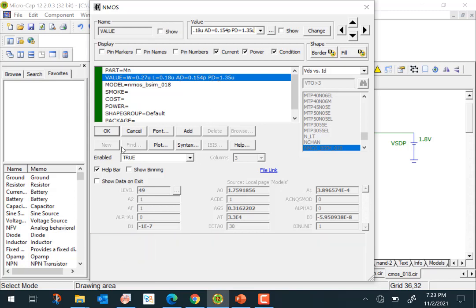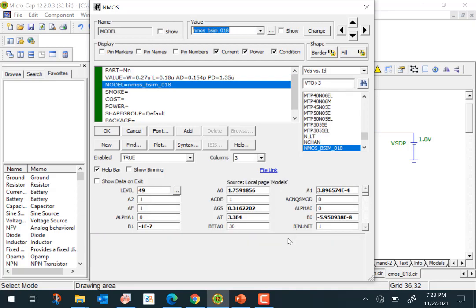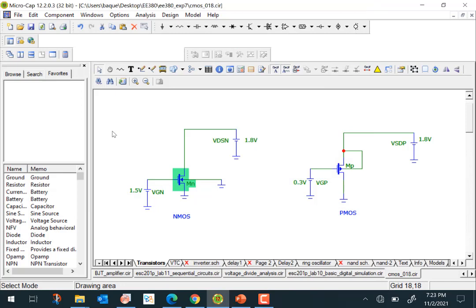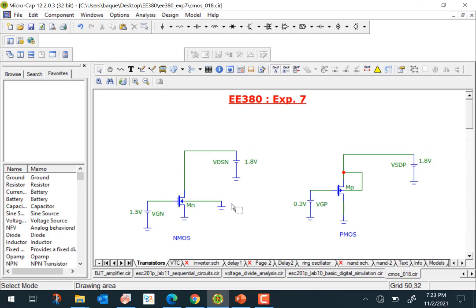Once you do that, along with the basic parameters that are there, the model is ready for you to simulate the transistor here. As an example, we have this NMOS transistor here. The body terminal is connected to ground. In this 180 nanometer technology, the usual supply voltage is 1.8 volt, which means that normally you would apply anything from 0 to 1.8 volt here. All right, so the supply voltage is 1.8 volt.